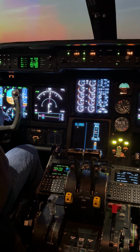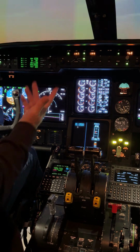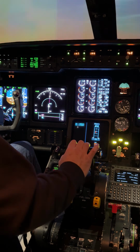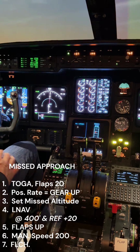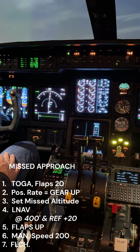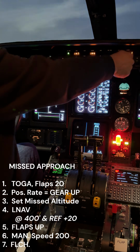And now we're coming up on minimums, and we can do one of two things. We can either land or do a missed approach. Let's see what a missed approach is all about. 400. There's minimums. So what are we going to do? It's going to be toga, flaps 20. Bring it right up. Positive rate gear up. Altitude should come up.